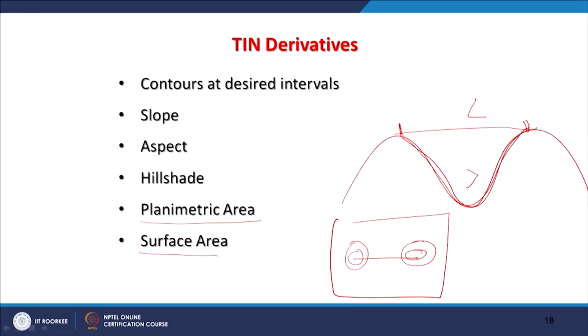One has to be very careful while calculating length, area or volume, because in cut and fill analysis, if a road is to be made in a hilly terrain, you must find the areas where the slopes will be cut and the areas where depressions will be filled. That is called cut and fill analysis.